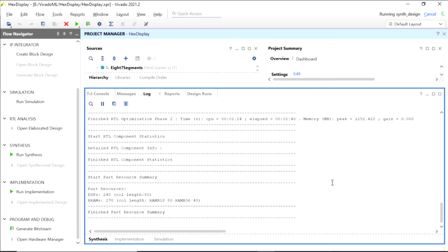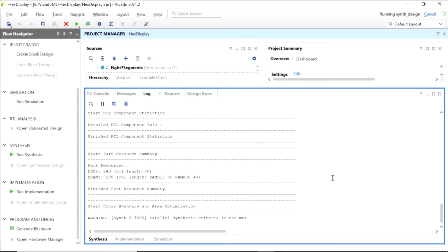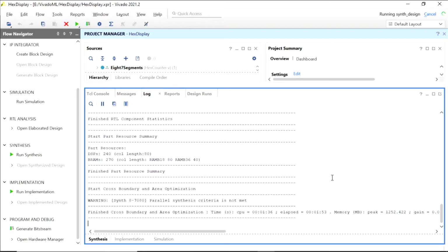Most of the time, for code that hasn't been finished, you'll get a lot of errors that way. But if you've tested it and run it through a test fixture or a test bench, and made sure that it looks right and that everything's initialized properly, then you can advance to the synthesis. Otherwise, you're just going to be spinning your wheels. You can go through the synthesis and you'll find plenty of things that you didn't catch, but it's slow.